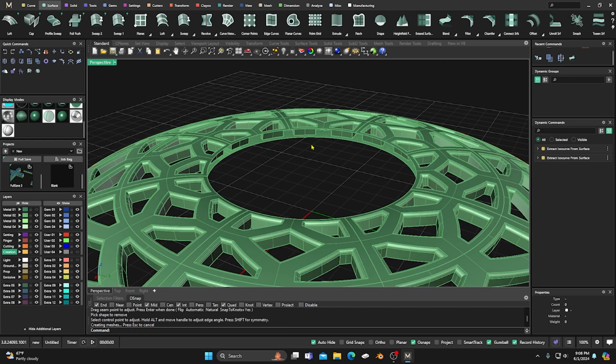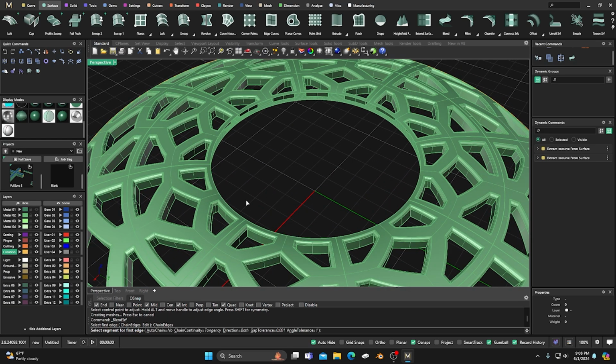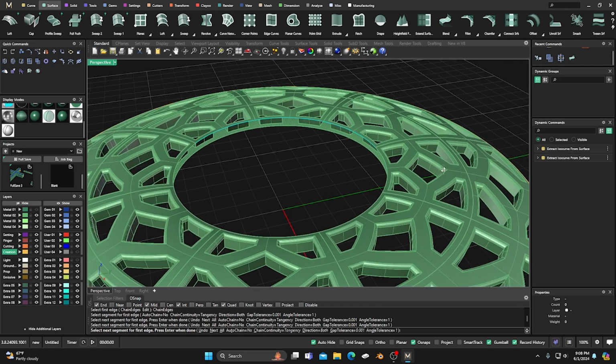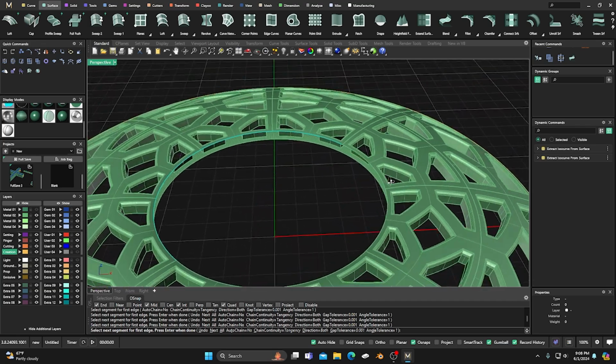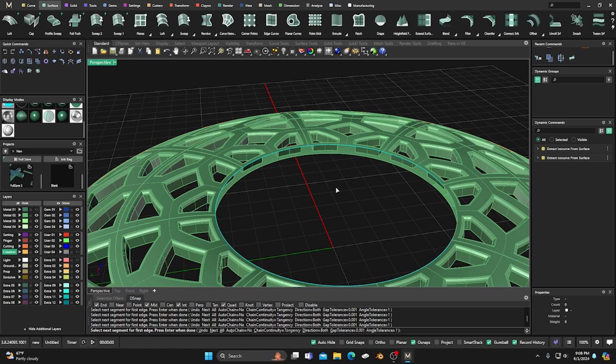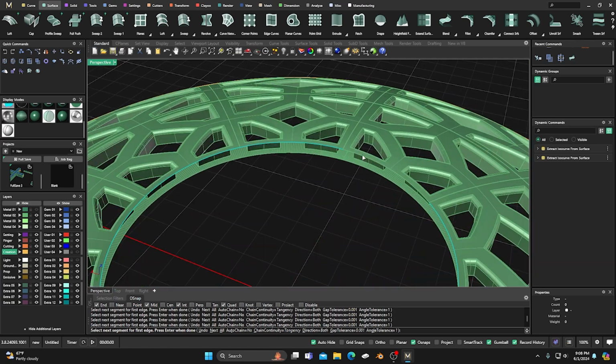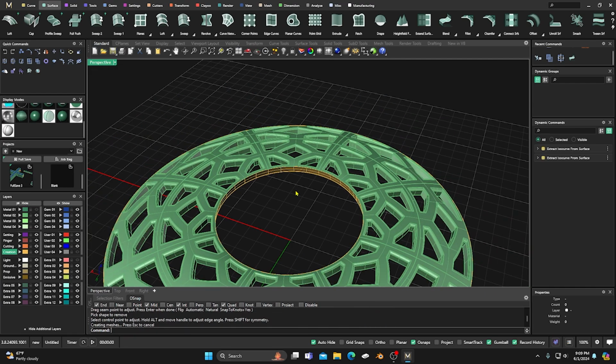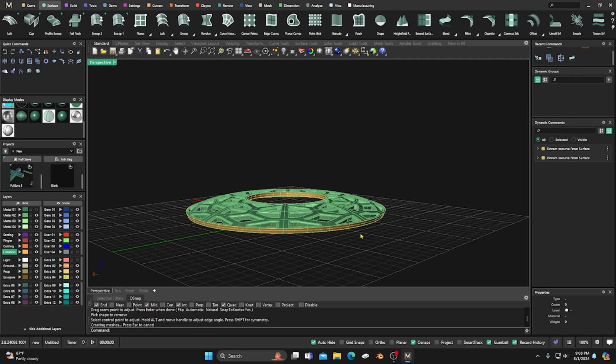And now we'll do the same thing. We'll right click and we'll go back to chain edges. And we'll go through here and pick all these ones at the top going around. Until it says select our second edge, and we only need to do that one, and it gives us that, and we'll hit enter and hit OK on that, right? So we have now closed off for the most part. So we'll select it all and we'll go to join, and it'll give us our surface there, right?